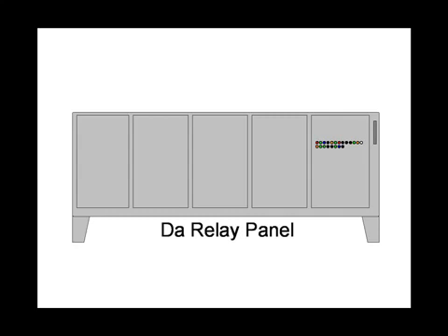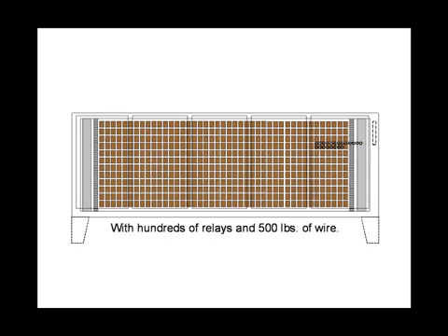To keep our illustration simple, we will connect all of the input devices, that is toggle switches, limit switches, photo eyes, etc., to a vertical terminal strip on the left end of the control panel, and then these terminal strips go to the coils on the column of yellow relays.